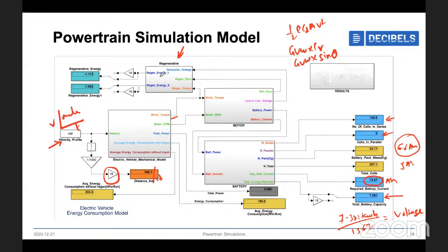Okay, so in the regenerative strategy, we also have to think about how much current the cell can take and all these things. So based on that, we have to give some torque limits on the braking side, and also, as I told you, we have to discuss the SOC strategy, which means from where we have to discharge the cell, either from 100 percent or from 95 percent.